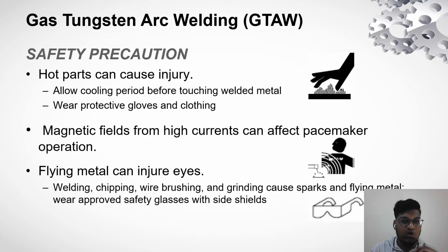And then hot parts can cause injury. Allow cooling period before touching welded metal. Magnetic fields from high currents can affect pacemaker operation. Flying metal can injure eyes. Welding, chipping, wire brushing, and grinding cause sparks and flying metal. Wear approved safety glasses with side shields.